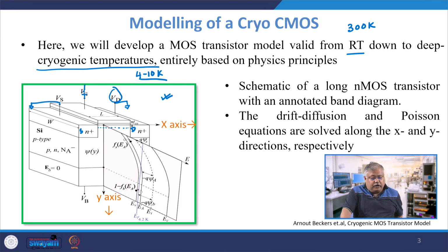If I also model such that my drain is first of all shorted with respect to ground, then as you all know, with applied gate voltage more than the threshold voltage, an inversion layer is formed, and the thickness of the inversion layer will be constant moving from source to drain side, because there is no bias on the drain side to deplete it. However, as you start making the bias on the drain side more and more, the thickness of the inversion layer starts decreasing as you move from source to drain, and it is eaten away by the depletion region. These are all basic stuff which you possibly already know by this time.